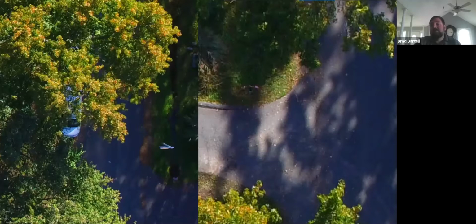These are essential to doing the photogrammetry ones. Not as essential when you start doing the RTK and LiDAR stuff, because you're already bringing the drone into RTK. So if you have an RTK service, which we already use, the Trimble KeyNet service, you're hooked right into that. If anyone's familiar with Trimble stuff, you have an R8, an R10, or R12, or an R2 running as your base with a radio, and that transmits back to the drone.